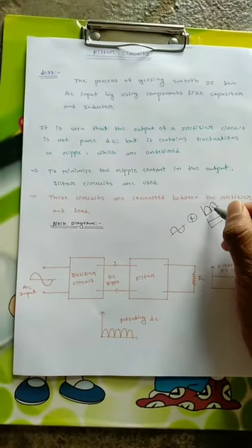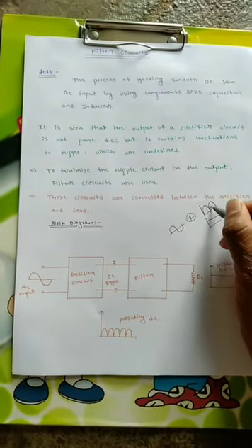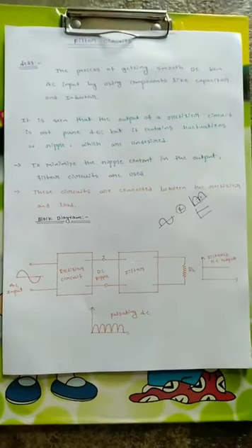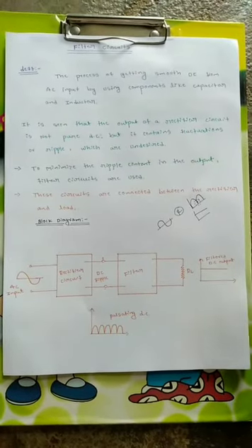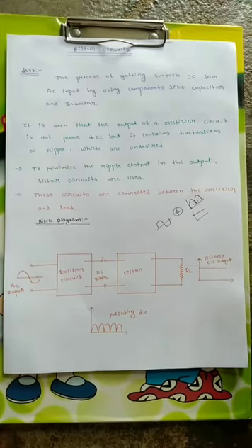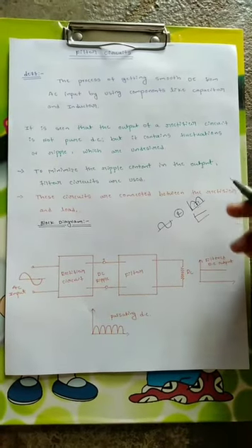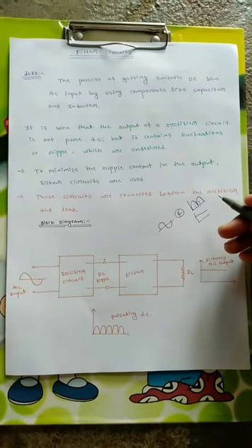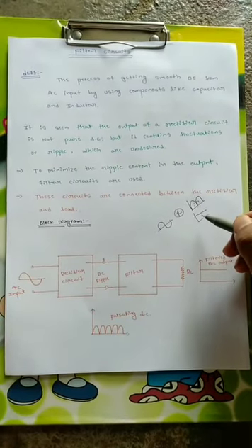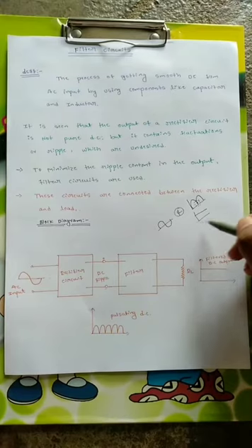This is the pulsating component here. This is not desired for DC-working components like a fan or any other device, because if the voltage is fluctuating, then the motor gets damaged. So in order to avoid that, we use filter circuits to get smooth DC.